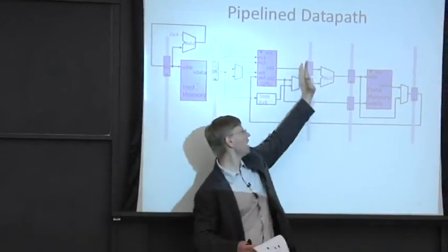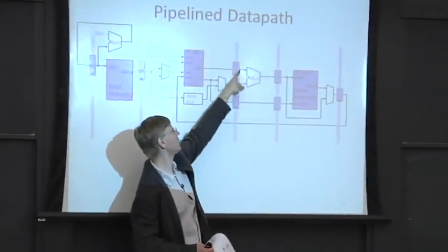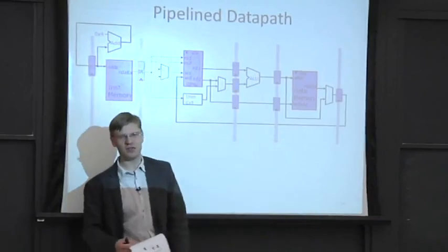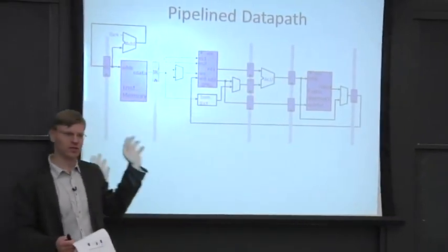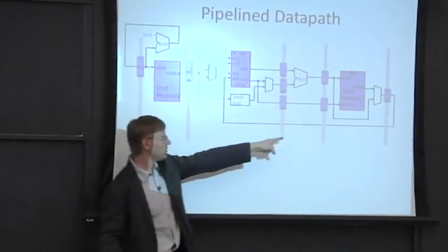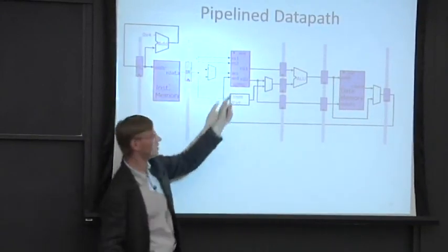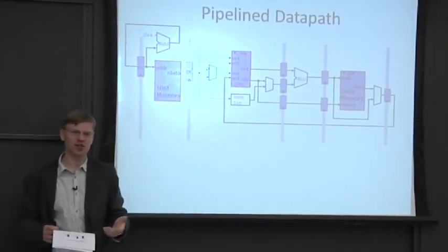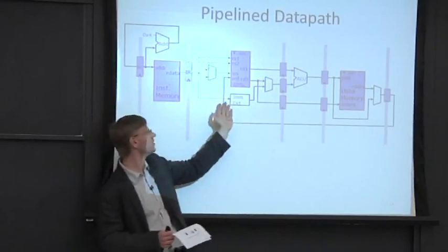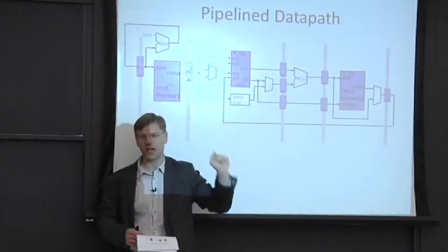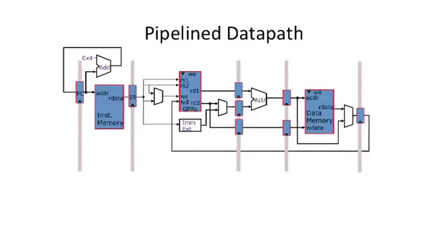So if we were to cut here, we need to put a register here, here, and here, because there's 3 sets of wires running from left to right. This feedback path here doesn't need a pipeline register because it's flowing back and effectively running back into the register file here, combinationally. And the register file can either be clocked or unclocked, depending on how you actually do this design.